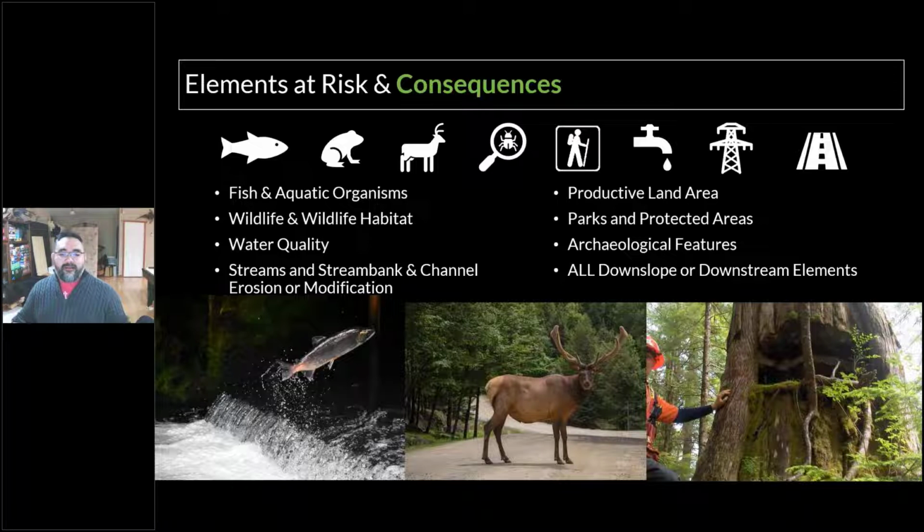So the other part of it is on the fish side. You think of stream hydraulics and how that impacts fish and spawning. So when you alter peak flows, you're going to alter how that bed load behaves, from the amount of it, to where it is, and its gradation. Different species of fish need different types or sizes of gravel to spawn in.